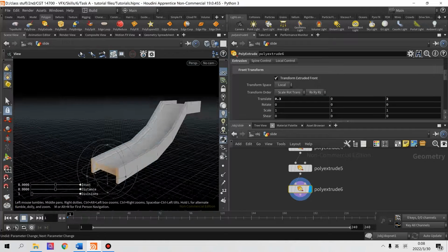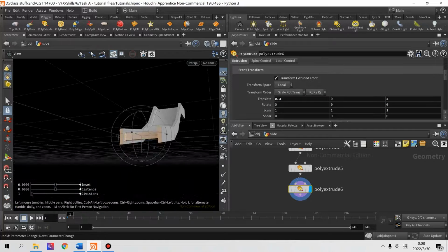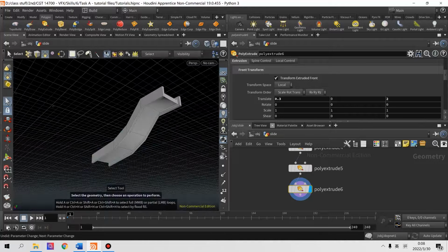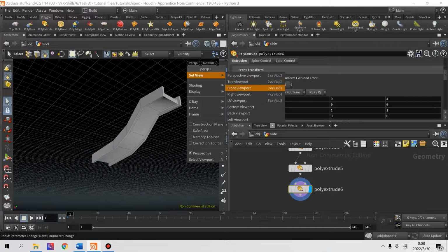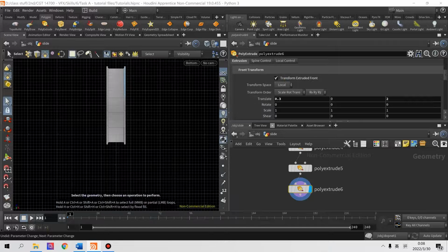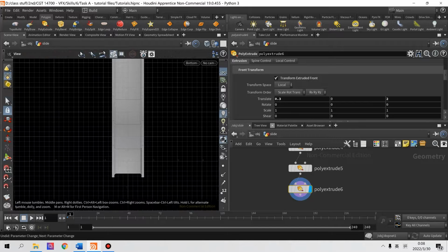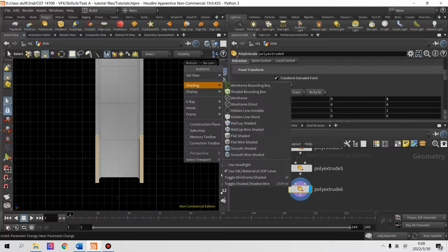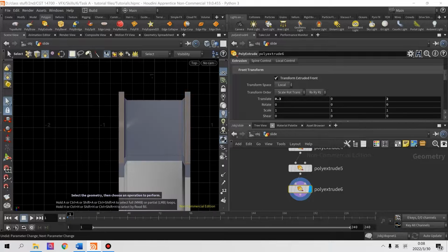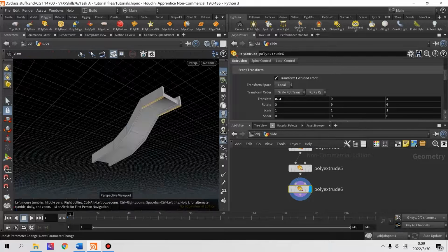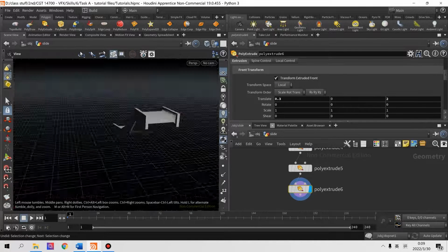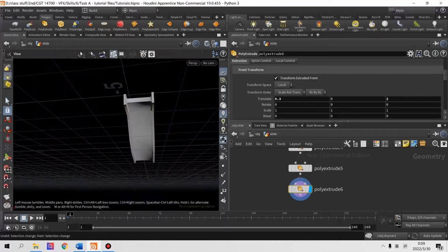And that looks pretty good. And then we're gonna create all the feet for the slide. So we're gonna use poly extrude node to some point of the slide to make it extrude down to the ground. But first I think we need to create the wall of the upper part of the slide, because there are always a wall to make for the safety consideration.